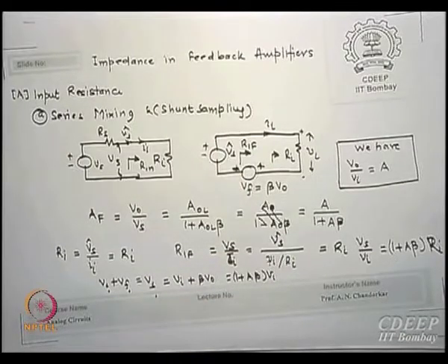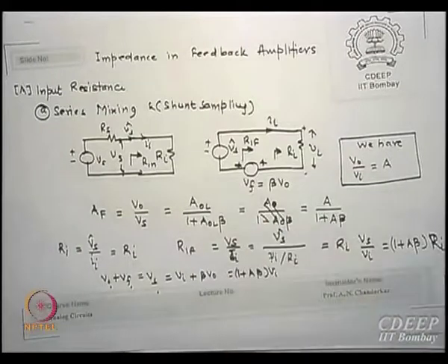No, actually we are not. What we are trying to say is, whenever I calculate input impedance, I don't consider the real source and its series resistance. Is that correct? There, the equivalent voltage that comes is what we call Vs hat. Is that clear? I am not saying Rs is 0, because tomorrow you will say, sir, you said Rs is always 0. Rs is never 0.